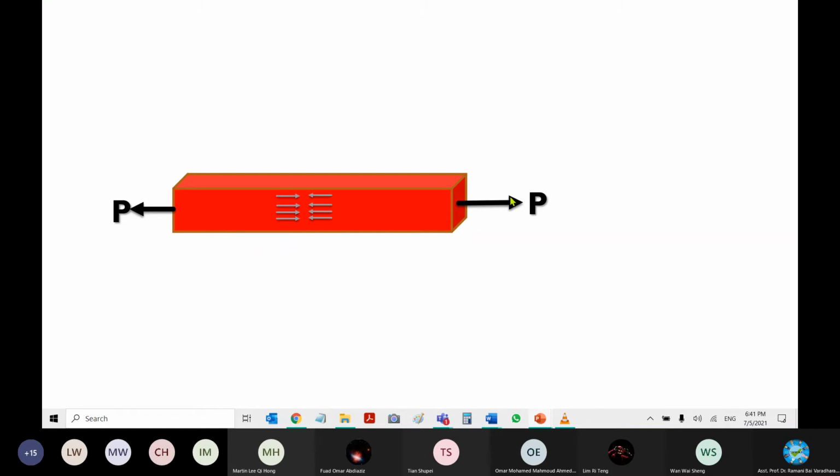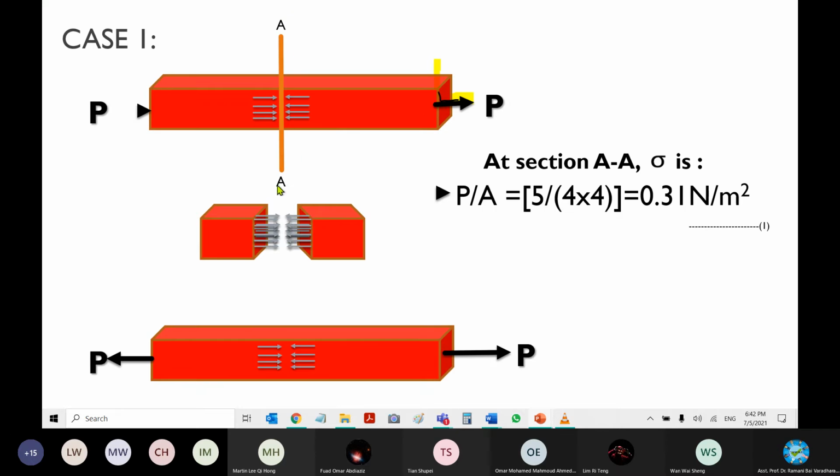Due to this, if there is nothing else, it will stop here. Because there is another load acting in this direction, the material in this area will tend to act in the opposite direction in this way. Next scenario. When you cut and take out the section, you may see it like this. This is called body response, or stress generated by the body due to its inertia, due to its material property. It may be brittleness, malleability, or ductility, right? Whatever strength it has, due to that, it can respond and try to restore the body to the original condition because it is going to neck, right?